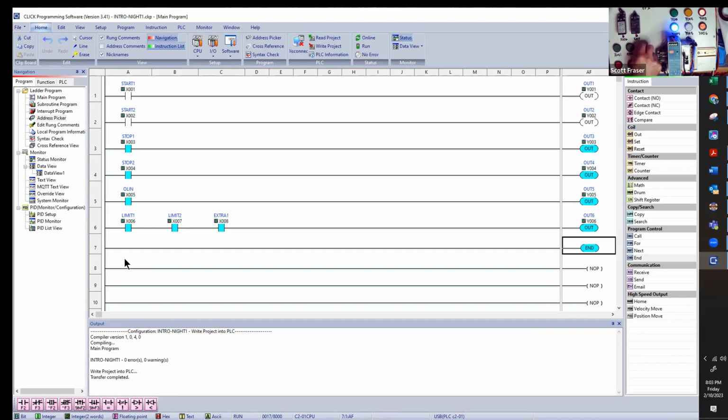Now this is toggle. Now, you notice that this light here is on because all 3 of these are on. If I push any one of them, okay, here's my limit switch, it turns off. Here's this limit switch, it turns off. Here's this button down here, it turns off. But I don't know which one it was. All I knew is that if any one of them goes, and so this might be like a safety loop right here.